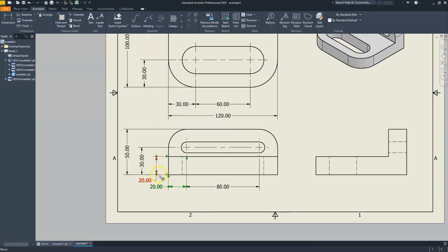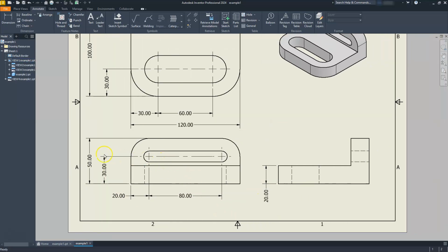Okay. Now, for example, you see these 220, where especially this dimension, I don't have to keep it there. If I place that dimension here, there is no need to double dimension this, right? So therefore, I can get rid of that dimension. Some other dimensions that I can get rid of, say I have this 50. And now let's go ahead and place that dimension along this side. So it's just depending on how you want to play with this.